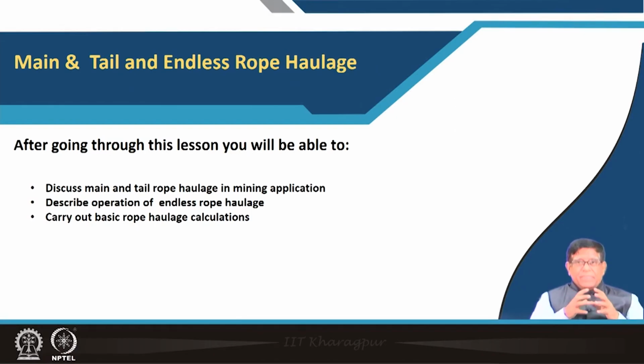When you are operating, you also have to see that no spark occurs. You will have to put in a switch, and when the switch is turned on and off, if any spark comes, it will be a problem. So the circuit by which you control that switch on and off has to be an intrinsically safe circuit.